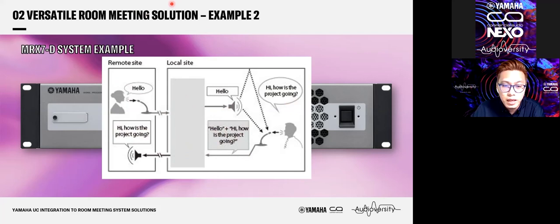Usually this type of echo can significantly degrade the intelligibility of the sound that is heard on the remote location. So this AEC effectively suppresses this type of unwanted echo, which helps to maximize clarity and intelligibility. Please note that this function is not designed to eliminate the room's own acoustic reflection and reverberation. The reverberation is handled by the de-reverberation feature instead.